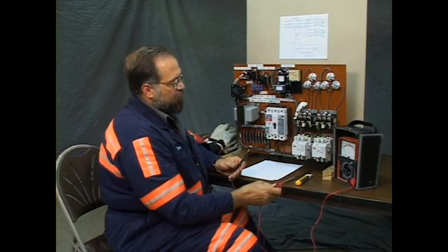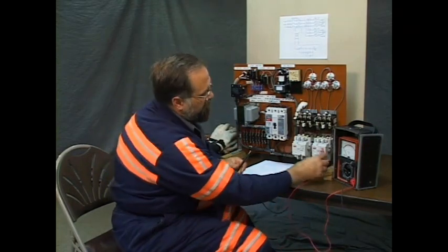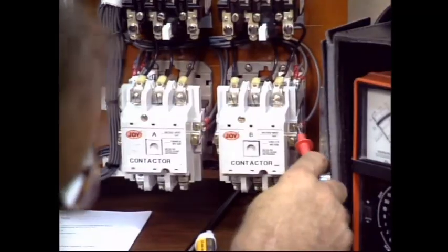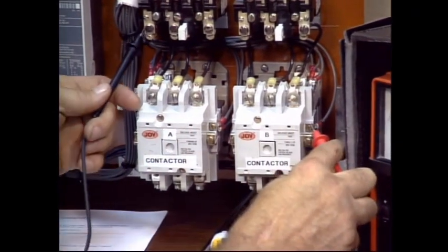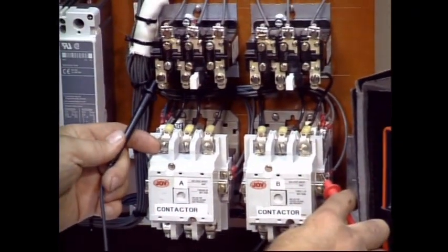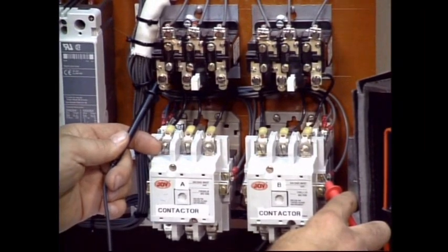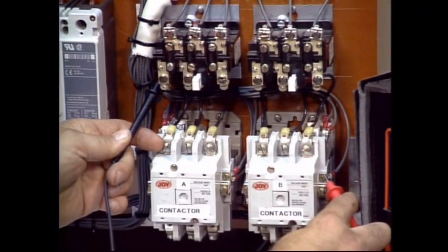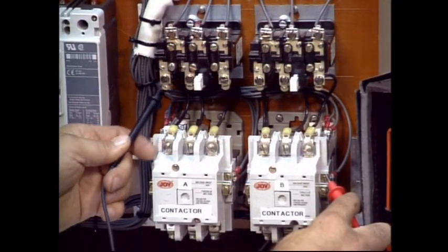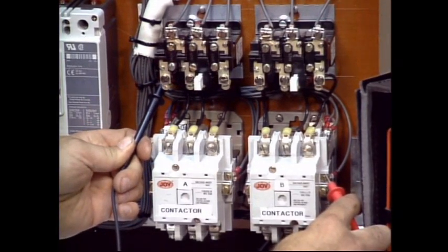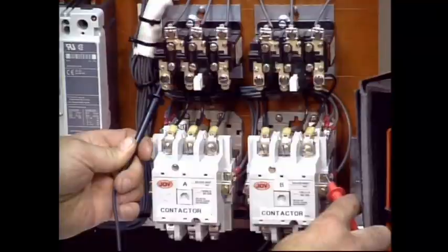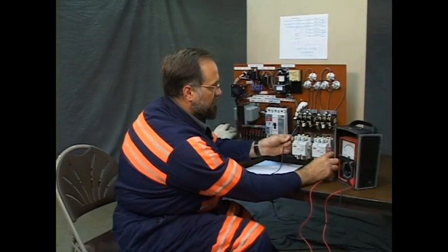This is the return side of the coil. After the work is performed, the electricity has to have a path back to the source, the return side. That's on the right of this particular contactor to AOL. There's a micro switch. Its terminals are underneath. I don't know if you can see those. AOL. It's not reading. It's showing an open circuit.